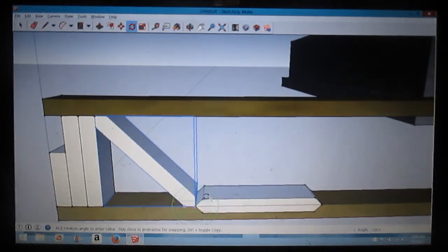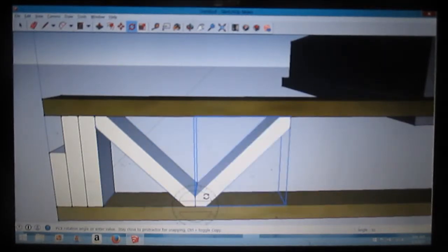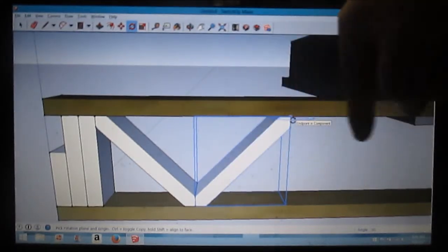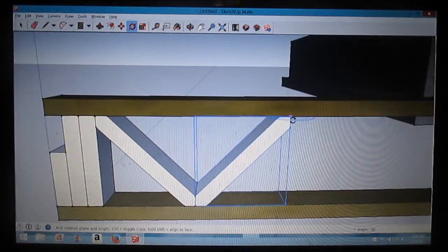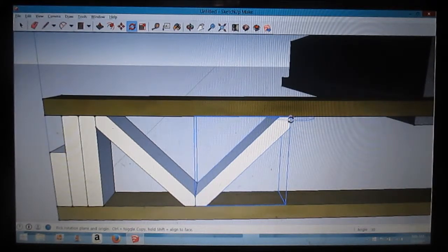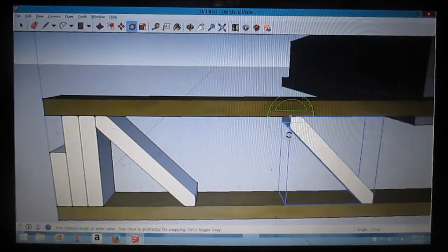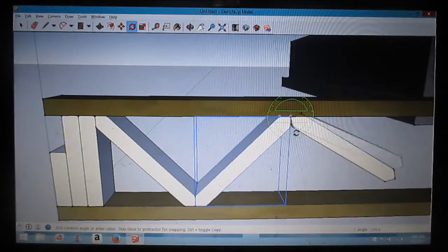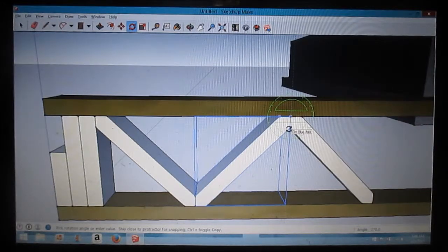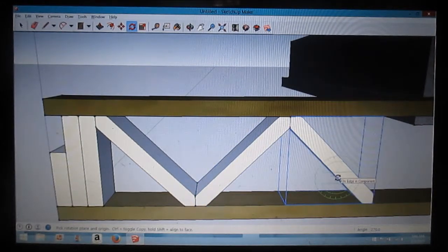Of course, if you overgo like that, and it says 135, you can just type in 90 and it snaps it. Okay, come over here, do the same thing. Go to this corner. You don't want it to be blue, because if it's blue, it's turning this way. You want it to be green, so you have to make sure it's green. Otherwise you'll rotate it the other way. And hit control. You can see that's 270 degrees. Snap it, I mean, just click it on your mouse.